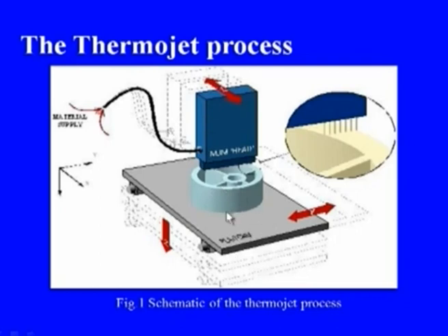Here this is the platform and this is the object being manufactured. And as I have indicated at the very beginning, this is a layer by layer manufacturing process in most of the cases. So, the material is getting deposited on this product and this platform will be lowered in a step, so that the next layer can be deposited on top of this.